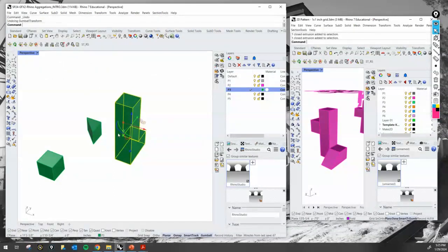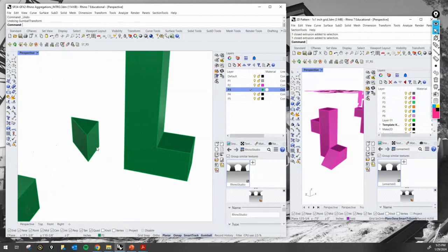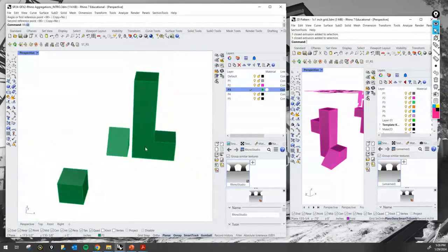Let's go minus 90 so that it ends up like this. And then we're going to pick up this wedge again with that rotate 3D. So I can select this object right here. This is my axis right here. And then again, for my rotation, I'm holding shift so that this constrains my cursor, and then hold shift one more time, and notice how that was lifted up.